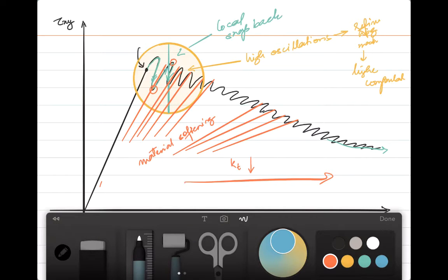So of course these results relate only to your cohesive zone, where you have these specialized elements introduced. So in a nutshell, you need to have a fine mesh, and when you have a fine mesh, you would see that your results are going to change. And instead of having such large oscillations, you will have smaller oscillations.